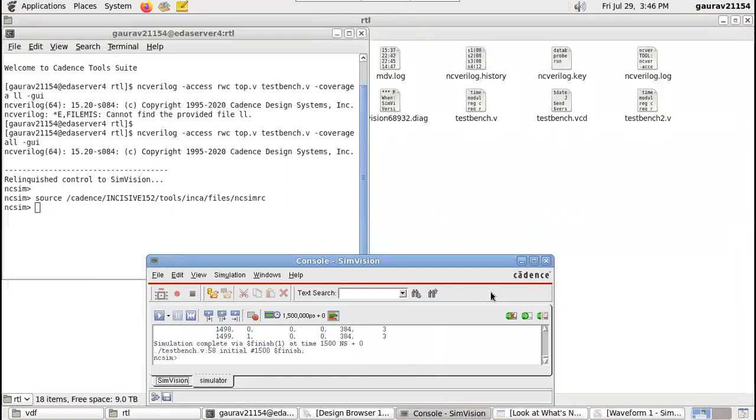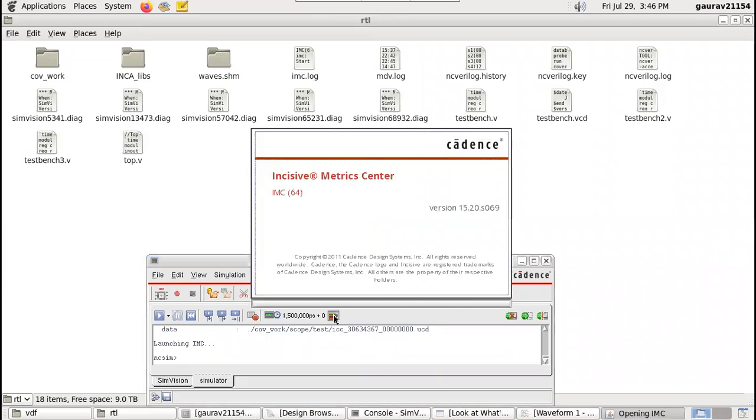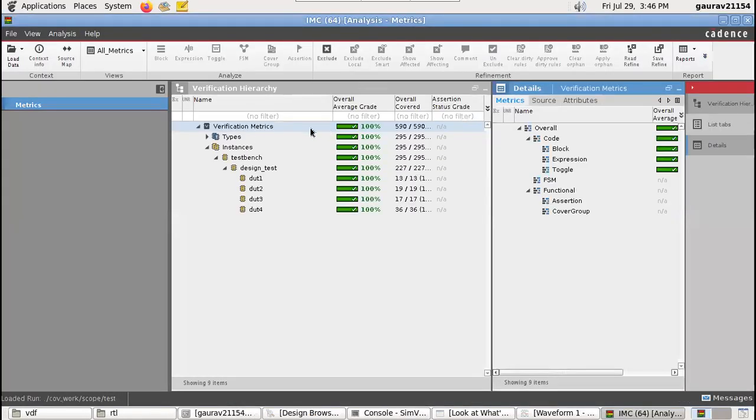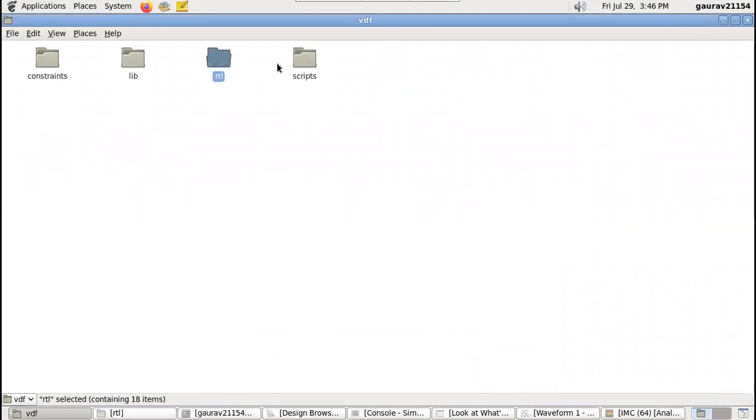That will be defined by code coverage. What is the code coverage of the test bench? Let me check whether it is covering all the test cases or not. See, the code coverage of the test bench is 100%, so each and every line of the RTL code is verified and working perfectly fine. If the code coverage of the test bench is 100%, then you have written a very good test bench. So now the RTL part is completed. We have the RTL code of our specification.